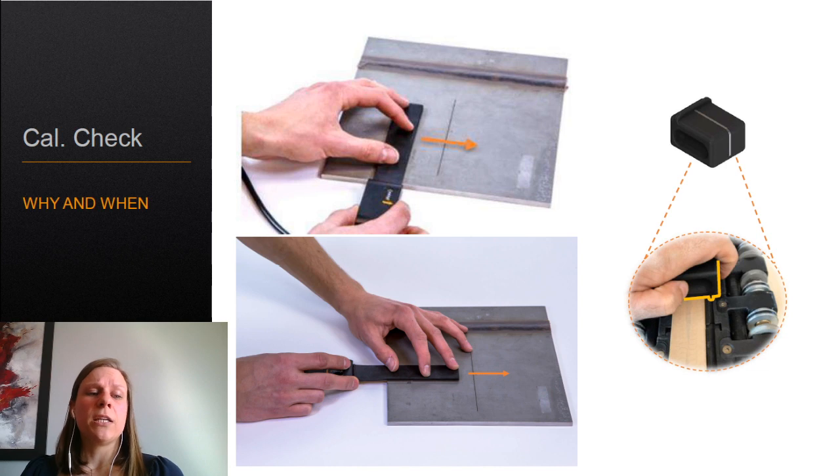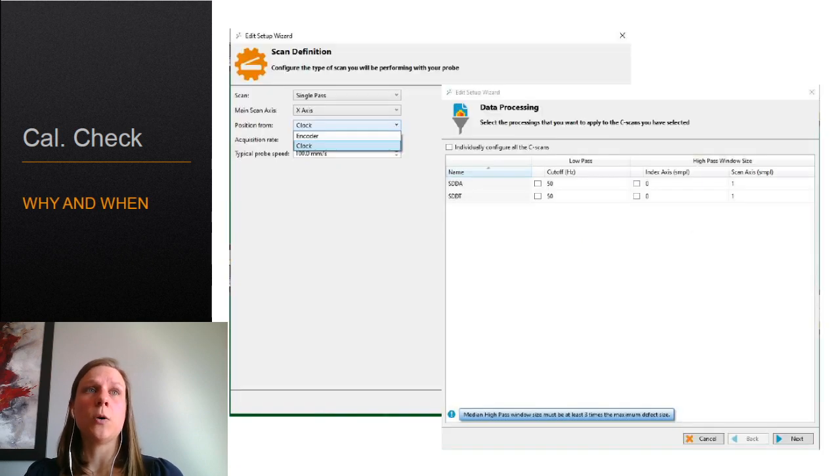I won't explain in detail why, because I already did for the Liftoff Assistant tool. But once again, if you want to get a good signal for your CalCheck, you will need to deactivate the encoders and filters. So the CalCheck is partly similar to the Liftoff Assistant tool in that it deactivates the encoder and filters and re-enables them when you exit the mode. So once again, a couple of steps that you won't have to manually do anymore.